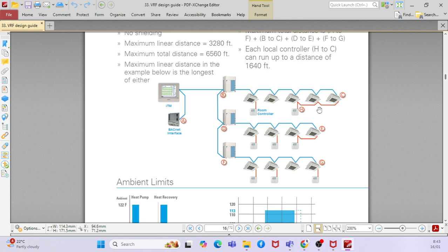But is this the package rooftop units that you're talking about? Yeah, this packaged rooftop unit, the length of the pipe between the indoor unit and outdoor unit. Okay, so that also they will consider the loss, but it is not necessary to enter the pipe length because you have to calculate the capacity only. But when you go with the manufacturer selection, you can tell them the maximum distance from one location to another location, then they can select the proper unit.